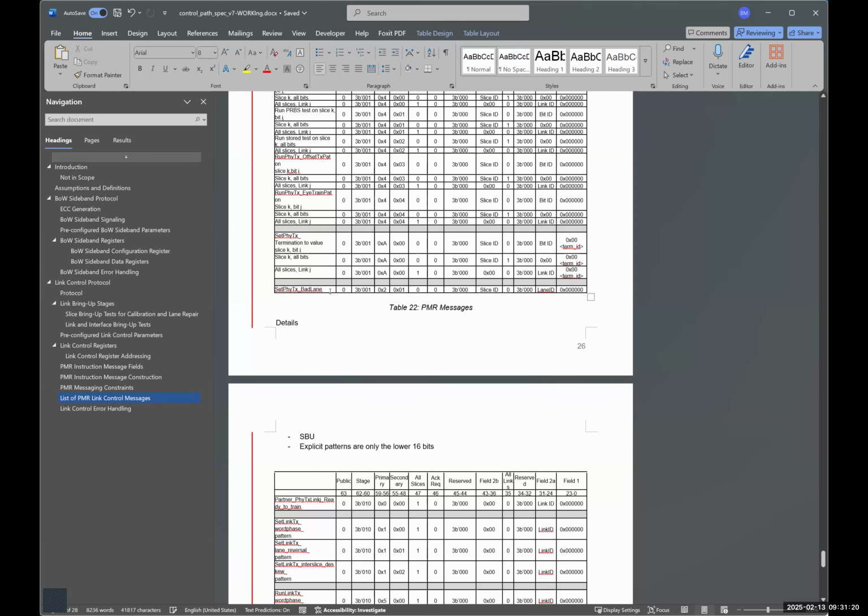So this is for the RX calibration. You need to terminate TX. There are two options: one is a 50 ohm termination, and another is a 150 ohm termination. This is with respect to the VREF calibration on the RX side, which requires the transmitter to be terminated with a certain resistance value. So this basically tells the transmitter to set the termination value to the correct mode, and then the TX can do its calibration on its side.